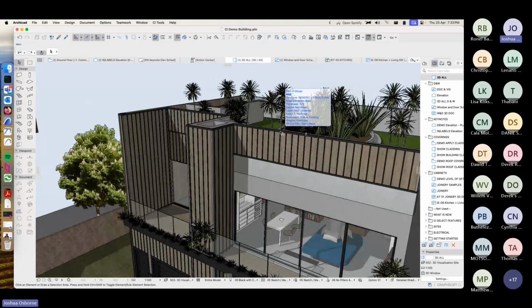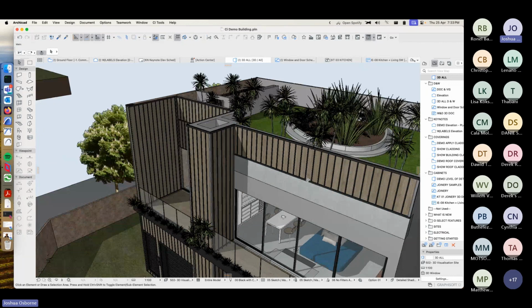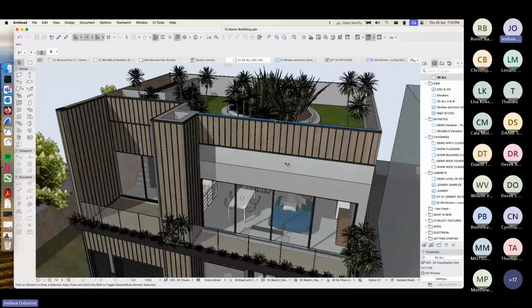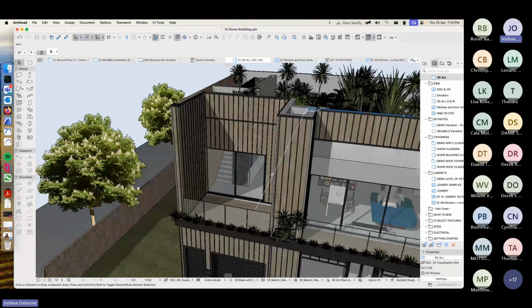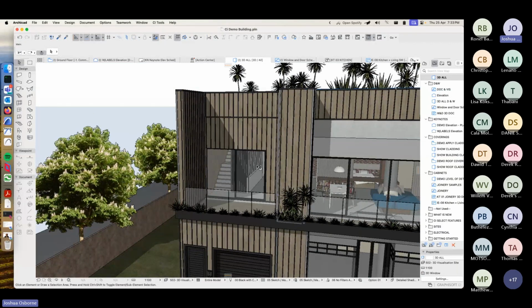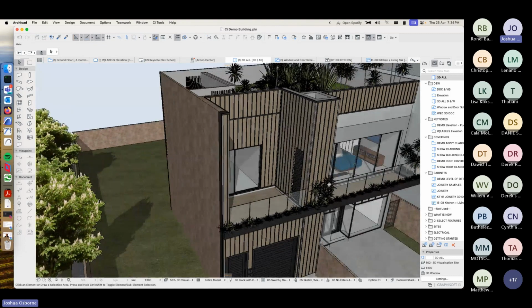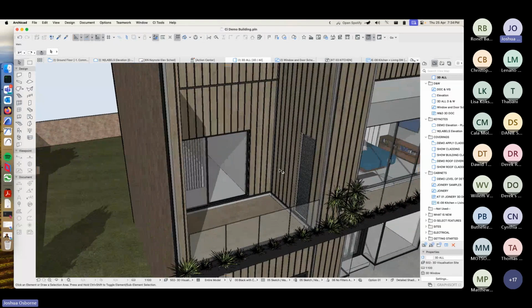So rather than putting a texture of some corrugated iron or some boards and battens in this case onto your project, or instead of painfully adding a bunch of slabs or tiny walls or something like that, you can model up that extra detail just by using the coverings tool to do that for you. And it's very simple to place, which I'll look at in just a second. Everything that is placed attaches itself to the wall that it is attached to. So you select a wall, you place your covering on it, and now that it's attached to that wall,